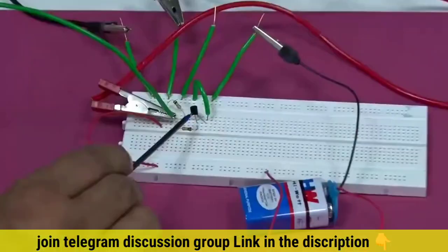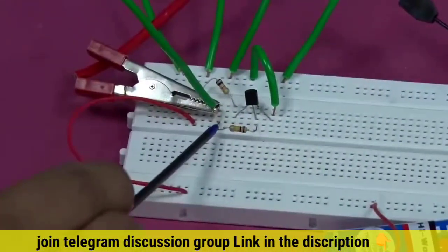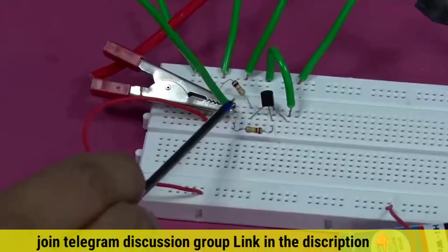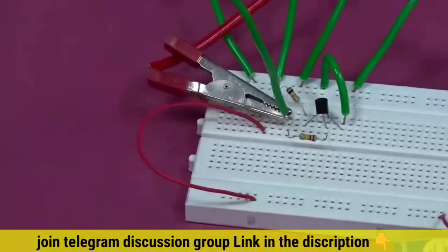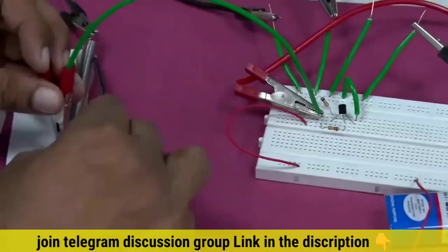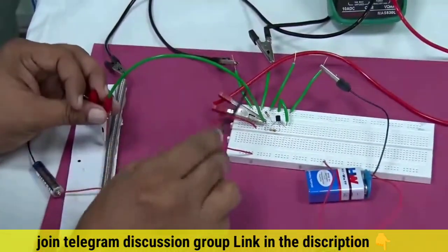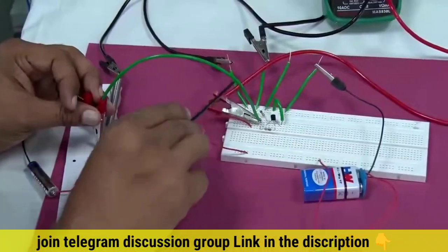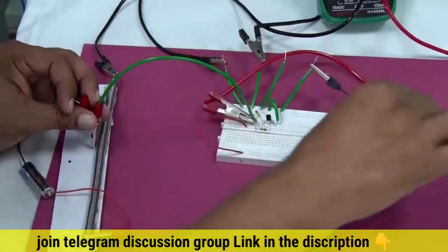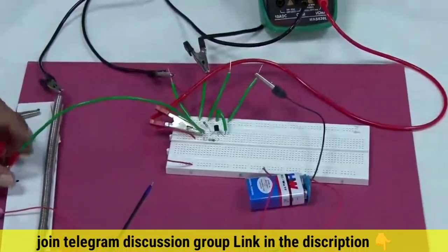Okay, fine. From the base it goes to 120 kilo ohm, and from the 120 kilo ohm it is going to the voltage. That variable voltage, the base biasing voltage, is being measured by this red wire, this clip here, and it is going into the multimeter. Okay. So, this is it.